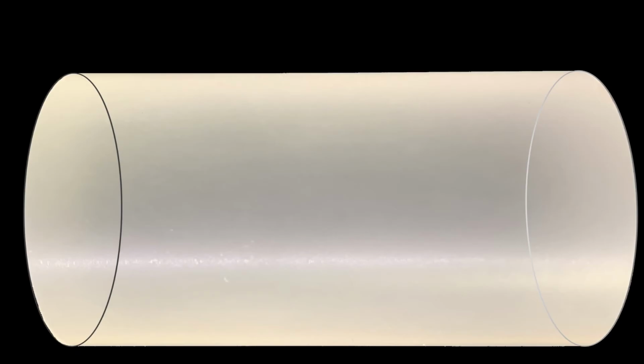When there are few defects in the processed core, their positioning to the cutting planes matters. Let us benefit from this effect. Knowing the precise defect coordinates allows calculating a core offset to position more defects into sawing gaps and out of future wafers. Let me illustrate the mechanism of such a gain with a simple animation.